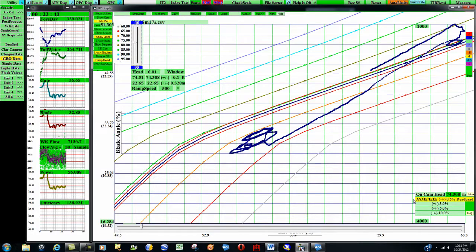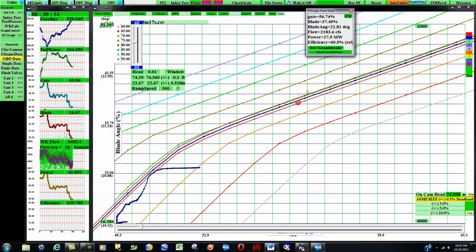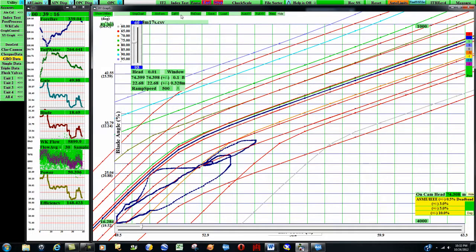Click on the Show Limits button to display the limits utility. The ASME 0.5% button displays the industry standards from ASME and IEEE that are intended to accommodate the normal slop and hysteresis in the mechanical section of a turbine control system. The 3, 5, and 10% limits are for evaluating tracking errors during rapid slewing from one power level to another. These limits are expressed in percent blade error divided by percent of gate motion per second.